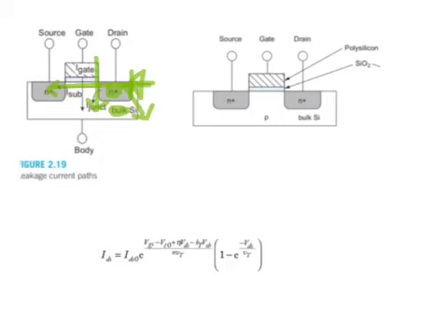So in this video we will be focusing on modeling only the leakage current that arises from subthreshold conduction, that is conduction from the drain to source without a proper formation of a conducting channel, that is for gate voltages between 0 and VTH.